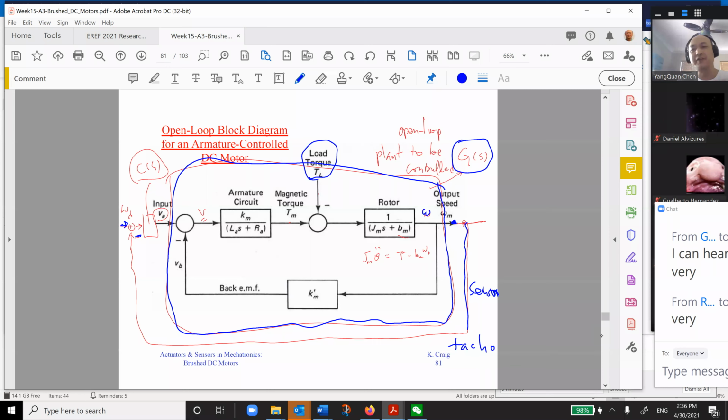So you feedback, there's an arrow in here, and with this arrow, we put the controller in here. If the desired omega is a constant, how do we make E infinity, the steady state error, equal to 0? We talked about it, right? Internal model principle or system types.